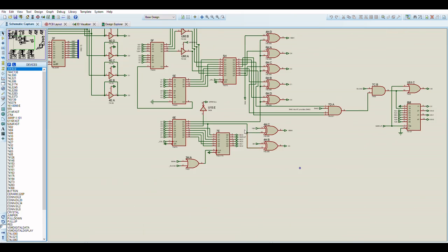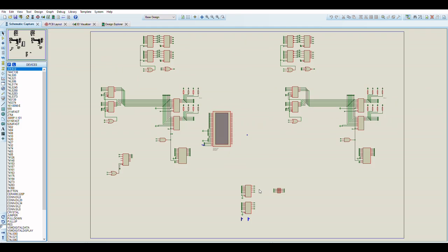And actually, I think I put it into the sprite flips and the sprite color, because at that stage I did not have a full screen height bit for the sprites, so I probably used this bit for the most significant bit of the sprite position.